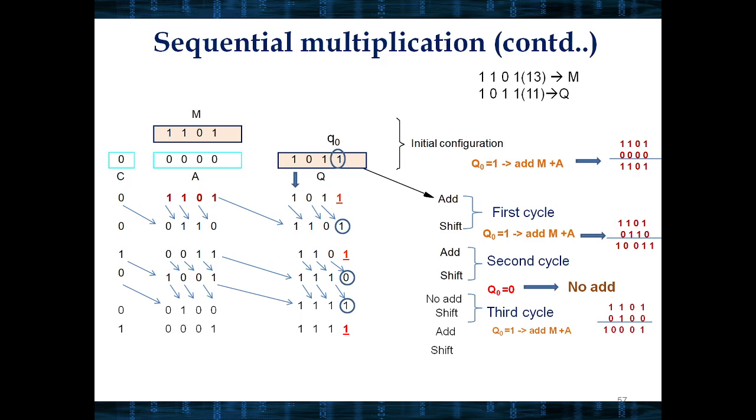So now you do the shift operation. When I do a shift operation, you will get these results as the partial product. So this is your fourth cycle. We are using 4-bit numbers, right? So 4 stages of multiplication will be done.